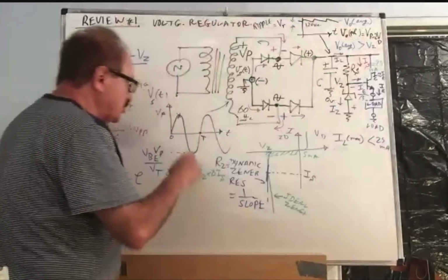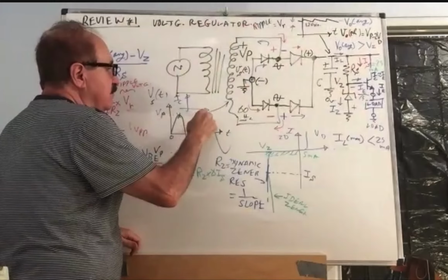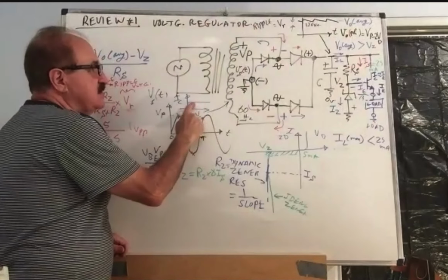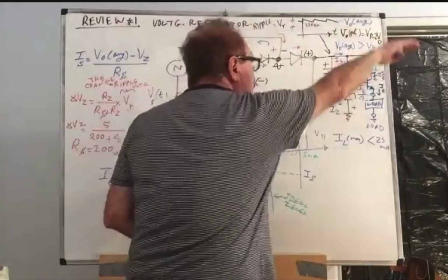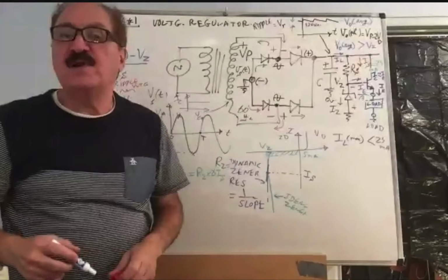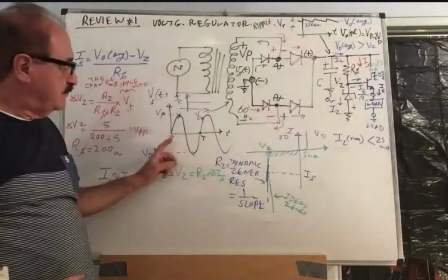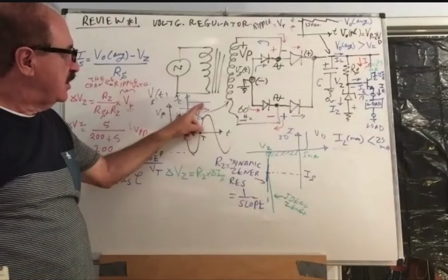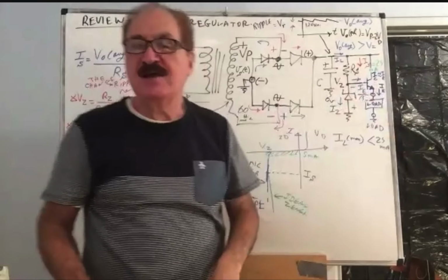Do you remember those curves? IC and the VCE, the lines were horizontal, nearly horizontal. So if the VCE is changing because of the dropping or rippling collector, the emitter will not change because the current doesn't change. Here, VCE changes, delta IC here. Current doesn't change, emitter current does not change. So the voltage will stay regulated.